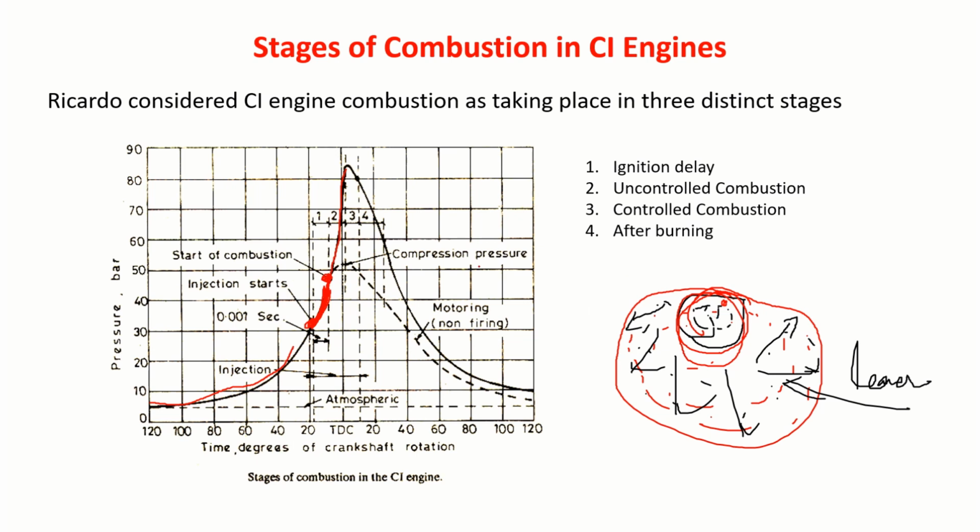Then, if you continue to inject the fuel, the flame front will travel and consume the charge. This is what you can call controlled combustion. A large amount of energy gets released, then this is what we call after burning. The ignition delay phase is uncontrolled combustion, because I've already injected the fuel, I have no hold on that.